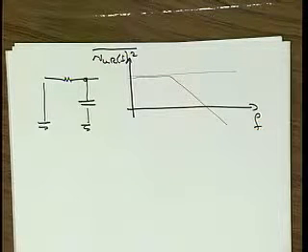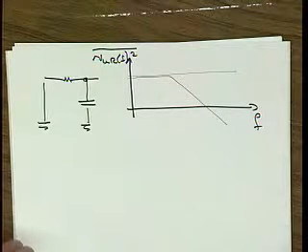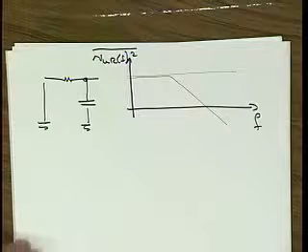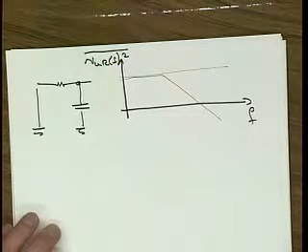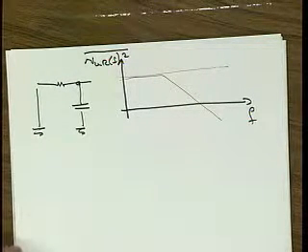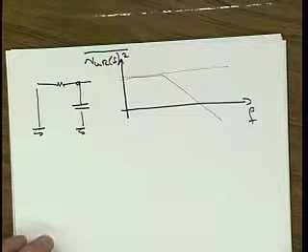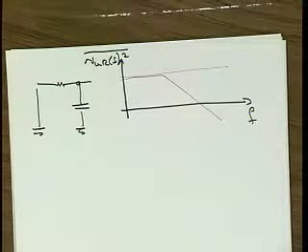So actually, if I haven't said that, I say now that the original thermal noise sources from a resistor or a diode or a BJT or MOSFET are white. But once the circuit acts on that noise, the noise is not necessarily white at all.